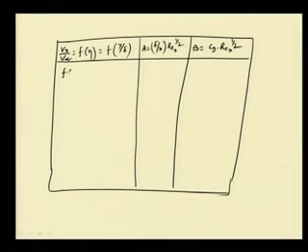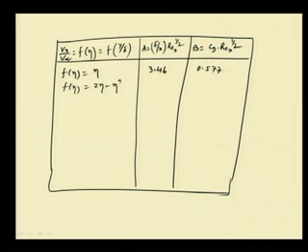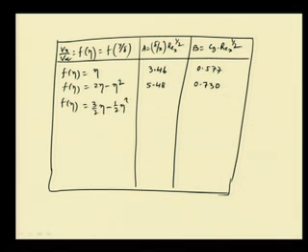So, f eta first case is equal to eta. It is a linear velocity profile in the boundary layer, and this gives 3.46 and 0.577. Then f eta is equal to 2 eta minus eta square, a parabolic profile, which gives 5.48 and 0.730. Then f eta equals 3 by 2 eta minus half eta cube, which we have discussed just now, gives 4.64 and 0.647.